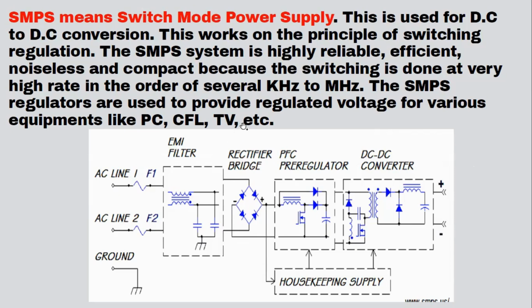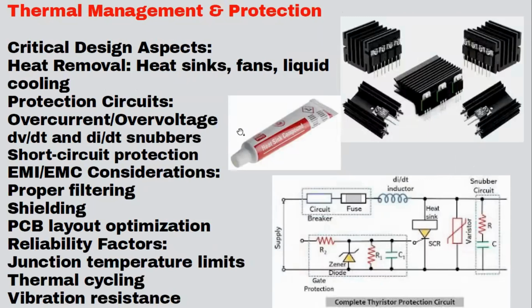Okay, the next topic is thermal management and protection. This is also very important, because thermal is a very important subject of your power supply, since we use components which get heated up. The critical design aspect is heat removal, that is the main work of thermal management. Heat sinks, that is aluminum plates of different shapes and sizes, are used. Fans are also used. Liquid cooling is also used. And heat sink paste, as we call it, is also used.